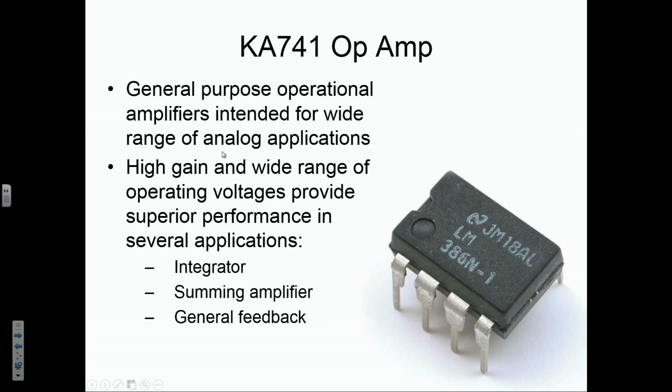Okay, so you need an op-amp. This is a good op-amp. It has high gain, which is good because basically you're wanting to produce a larger signal with a smaller control signal. It also has a wide range of operating voltages that provide superior performance in several applications as an integrator, as a summing amplifier, and for general feedback.